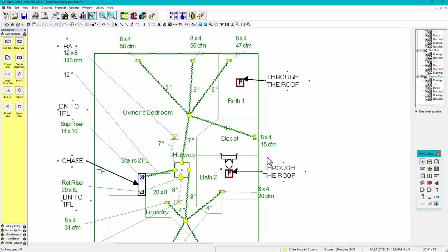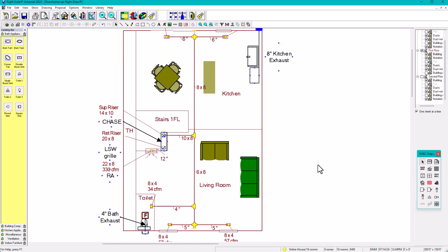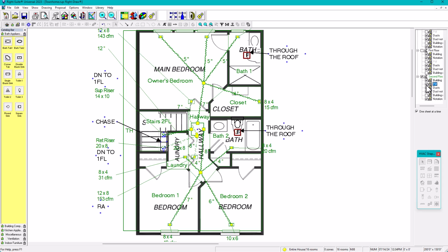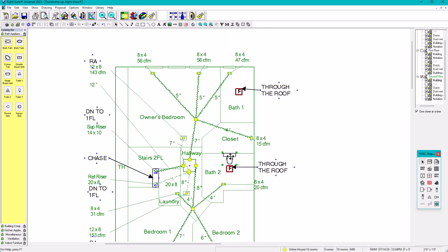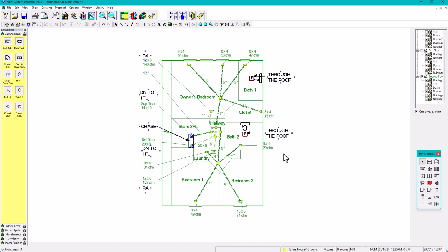Toilet. Again, this is not needed, but it's for consistency, because whenever I'm reviewing some drawings, or someone else is, they'll see, okay, there's a toilet here, an exhaust fan. In here, there's an exhaust fan. Where's the toilet, right? So consistency is very important. It's to show professionalism too, okay? So now let's go here. We can copy and paste the same toilet, and then I'm going to rotate it 90 degrees. We're going to put it right there. Toilet. There we go. It's done.